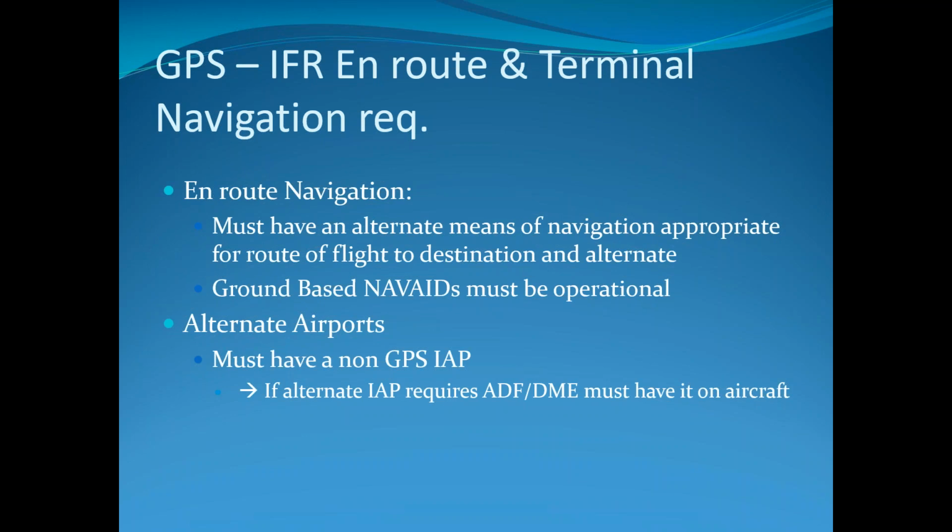That's what the IAP stands for. If the alternate instrument approach procedure requires ADF or DME, you must have it on the aircraft. So it's basically saying that we have to have ground-based backup wherever we go. Now that is changing as we move on and progress in the aviation world.